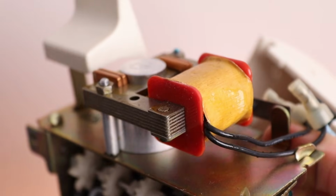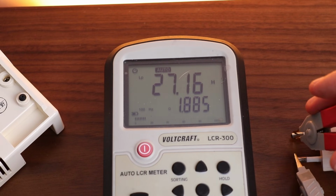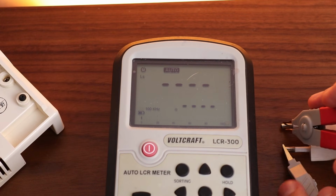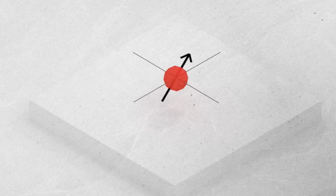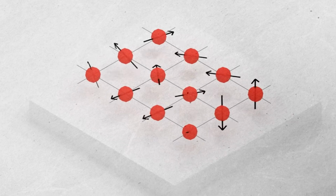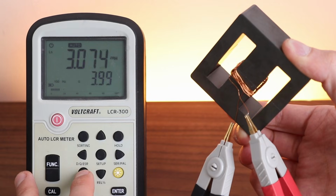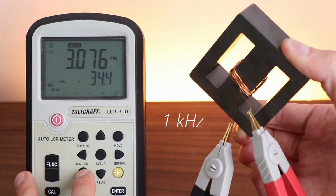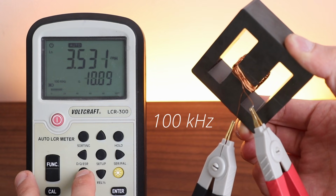Here I've got a laminated steel core, which is usually used for low frequency applications. If I measure its inductance at low frequency, the value is quite high, but at high frequency it becomes very small. Why is that? Because the magnetic dipoles inside it are slow. They are like a turtle compared to ferrite, which is a cheetah. A turtle can move fast enough to handle 50 Hz, but once it has to deal with hundreds of kHz, it just can't. In contrast, ferrite has dipoles that can easily reorient at frequencies of hundreds of kHz. That's why its measured inductance at high frequency is still very high.